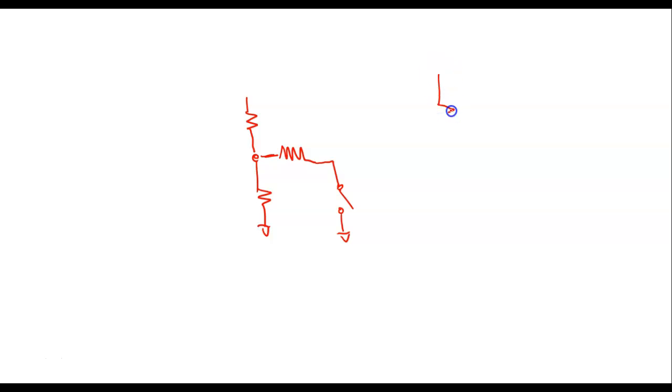So what do we use this thing right here for? Of course, what's this? What's that the symbol for? A what? Well, this is what we call a rheostat. So we use a rheostat to control the current. In fact, you very seldom see rheostats because this next component, we can make it serve two functions. We can make it work as a rheostat, or we can use it. So this is the guy I'm looking at. So we'll have to add one of these. And what's that? Potentiometer, right? A potentiometer is a variable voltage divider.